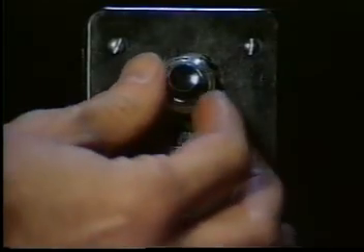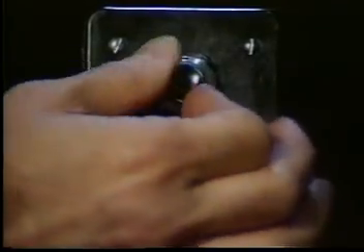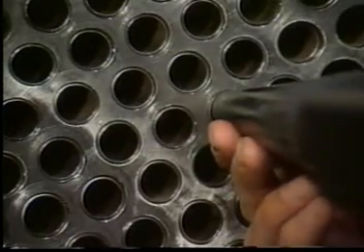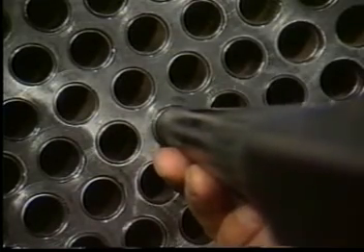For central areas, bring the Ultraprobe sensitivity back up to normal. You may also increase the amplitude of the tone generator as the distance away from the vibration area increases. Use this method to check the integrity of the tube roll. Grossly thin spots along the tube will vibrate and therefore may also be recognized.